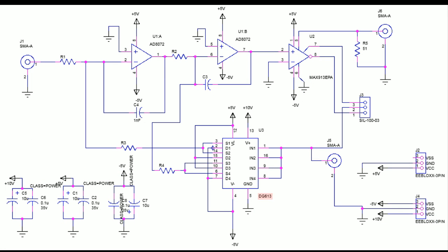The first schematic I showed you was called a single order modulator. Here's a dual order modulator, which means we've got 2 things going for us: 2 integrators, 2 feedback paths going on. With the second order it can either do something much better than a first order, or if you screw it up it can do much worse. I just wanted to show you this because we did build one of these. Unfortunately we didn't have time to really go into it in time for this video.